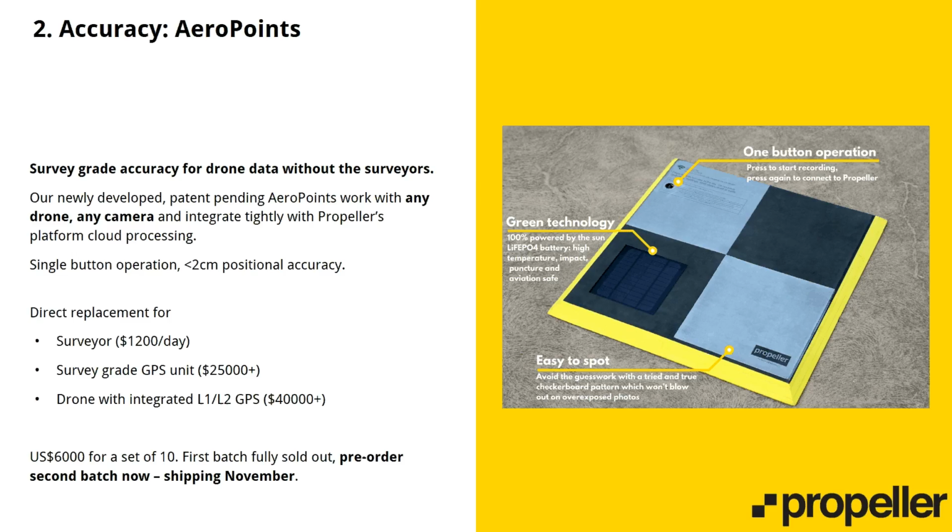The other big one is the AeroPoints, and this is addressing that accuracy concern. I've actually got one here. What they are is your traditional ground control points, your white painted cross on the ground, but instead of needing the RTK GPS unit, the rover, to capture the center of the point, it's actually got an RTK GPS unit inside it, okay? It's very straightforward. It applies all the same RTK principles that some of us probably know, getting centimeter grade GPS information.